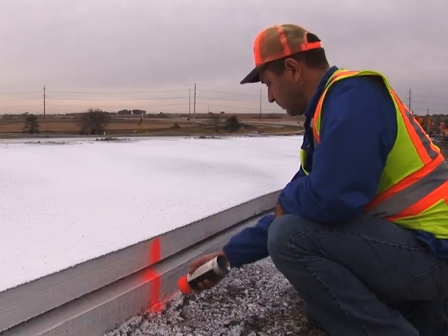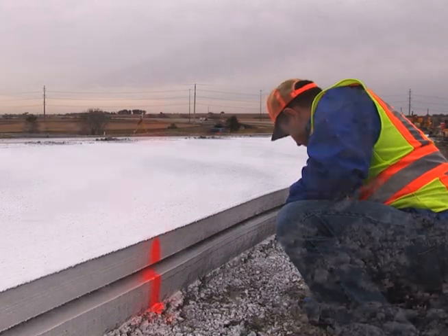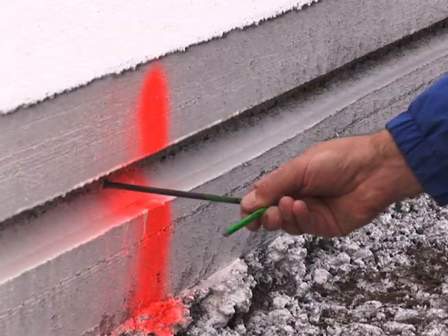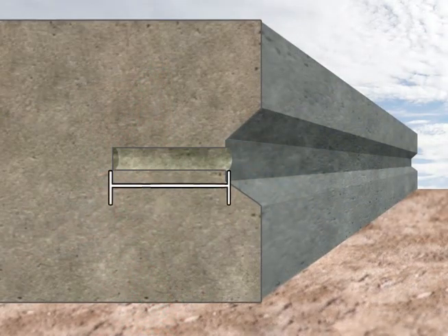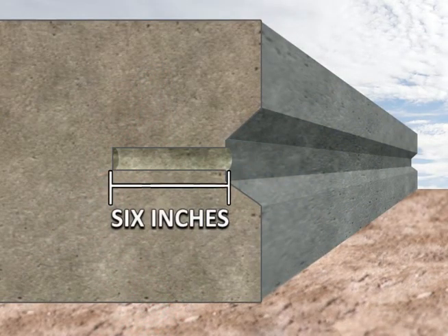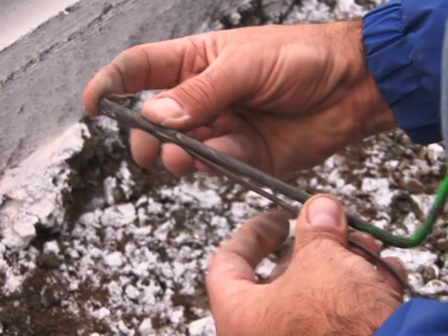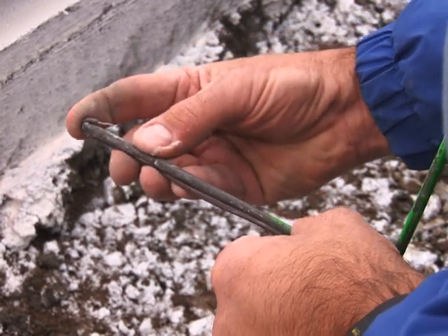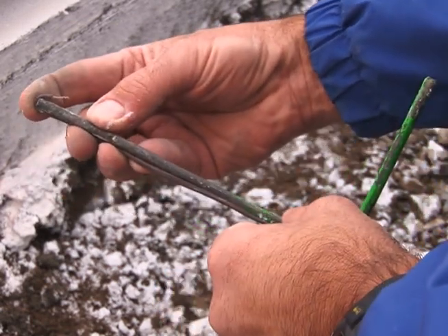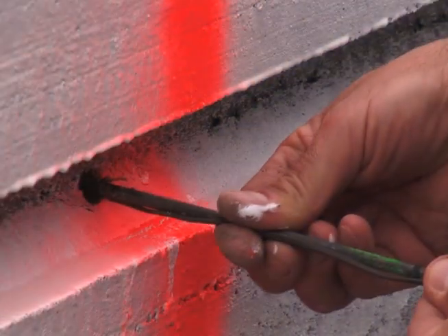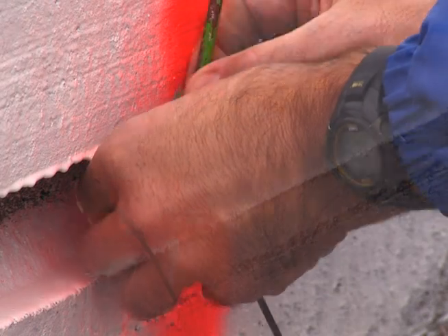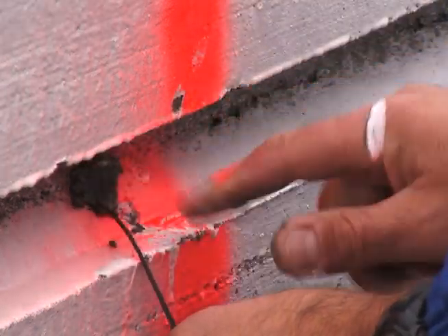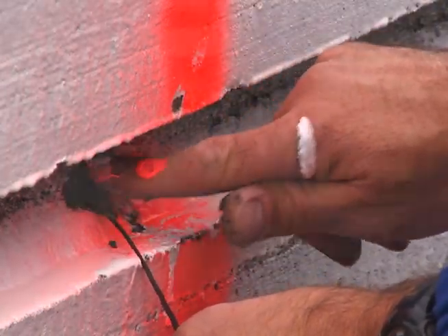After the location has been determined, mark the area. Next, by using a heavy gauge wire, penetrate the side of the slab to a minimum of 6 inches at approximately mid-depth. One method to install the wire into the slab is by placing the wire over the tip of the heavy gauge wire. Next, proceed to insert the thermocouple wire into the existing location. Then, utilizing fresh concrete, fill the void around the wire.